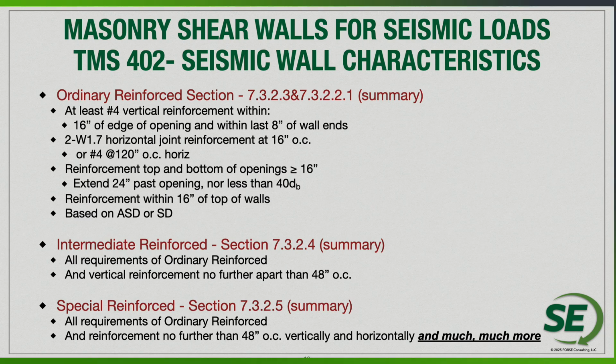For intermediate reinforced masonry shear walls, which again gives us a higher response modification factor, so a lower overall seismic design force, a more ductile response.